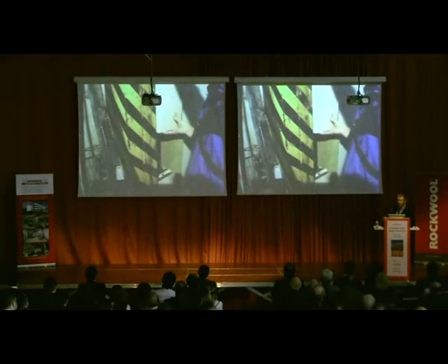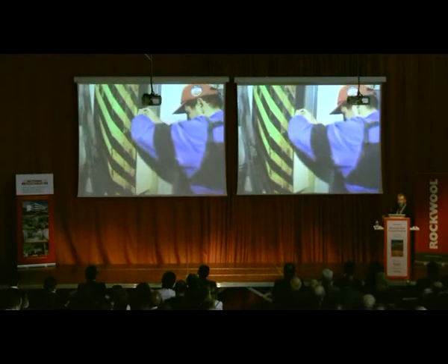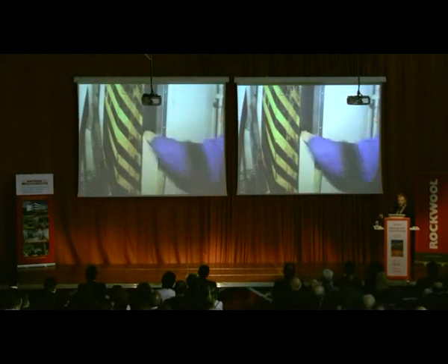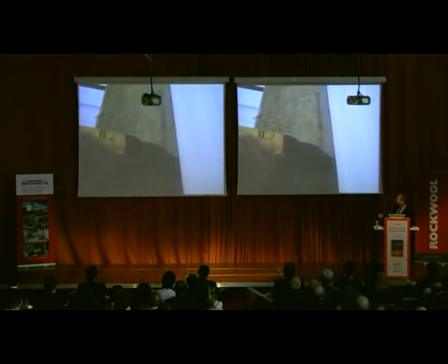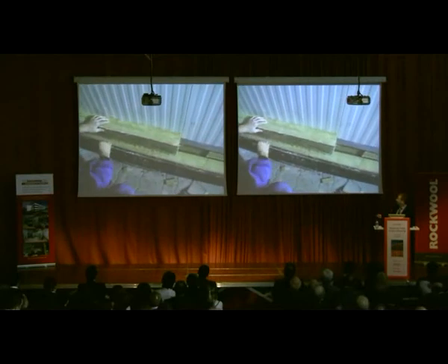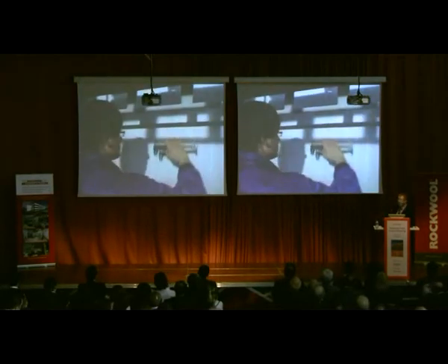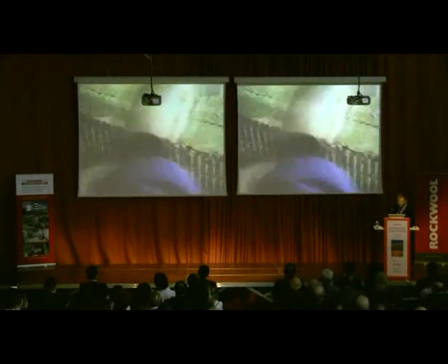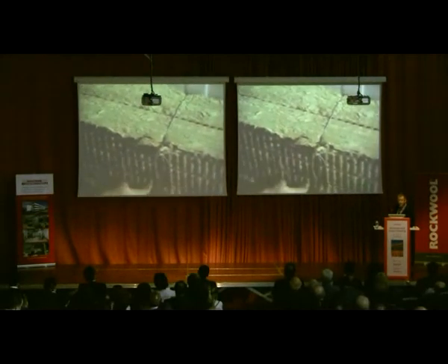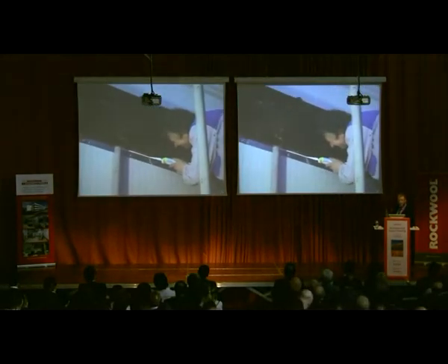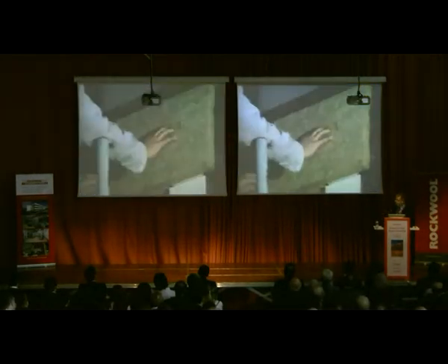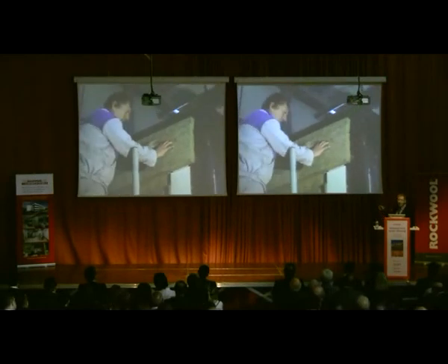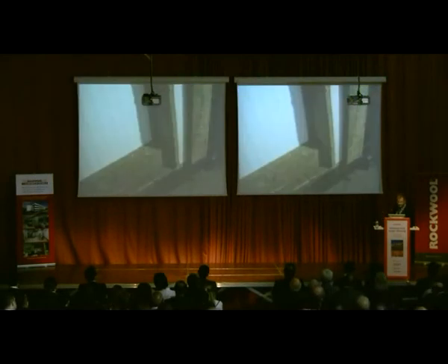And now these panels are screwed to the steel load-bearing construction. So there is a load-bearing element on the top and on the bottom, steel profile. And this steel profile is insulated from fire, usually by stone wool, so that you don't have any deflections, any deformations during the fire test. And it's very important to seal any kind of gaps so that fire can't penetrate through this construction.